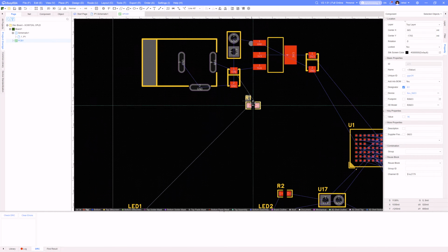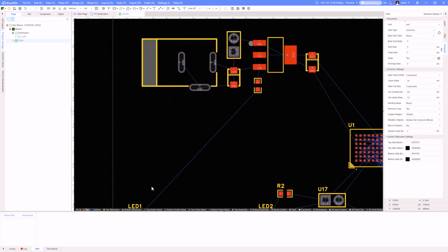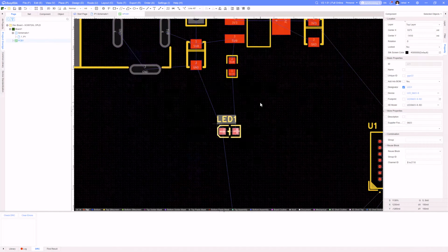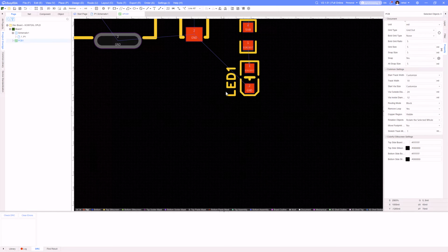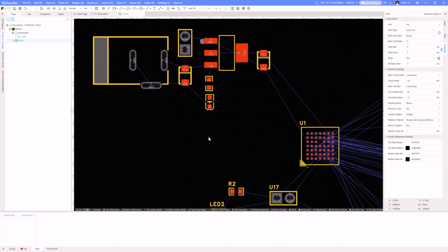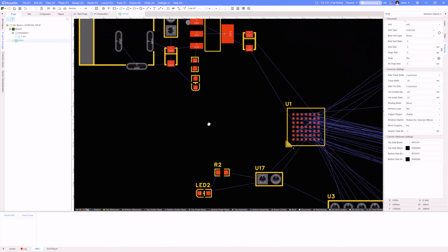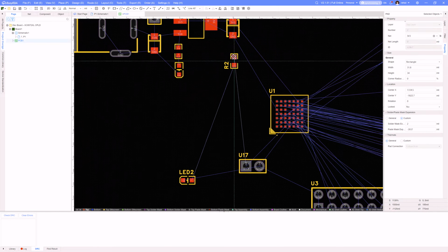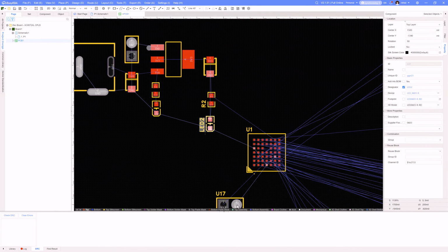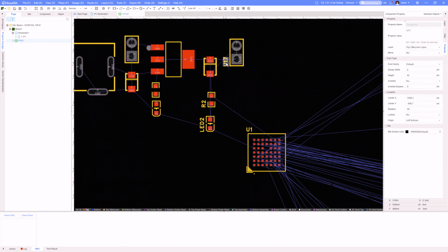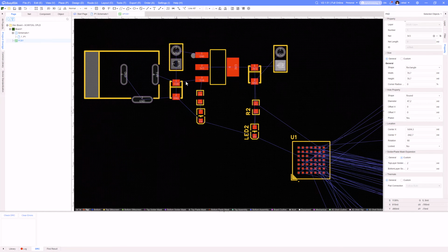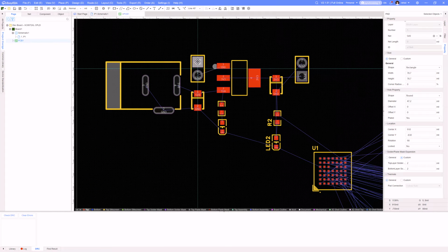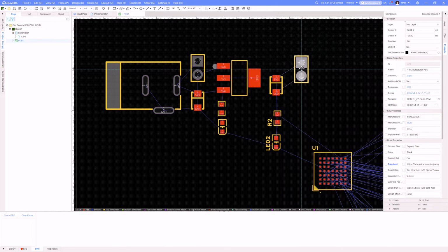And then on my 5 volt, I want to show that I have power with a little LED, which is going to go to ground. So I might just come in here and say there is my indicator for 5 volt. And I could probably mimic all of this for the 3 volt. So let's come up here and say, here is this. And I like grounds towards the bottom, so I might just turn this around like that, which I don't think will be a problem. We can deal with that.